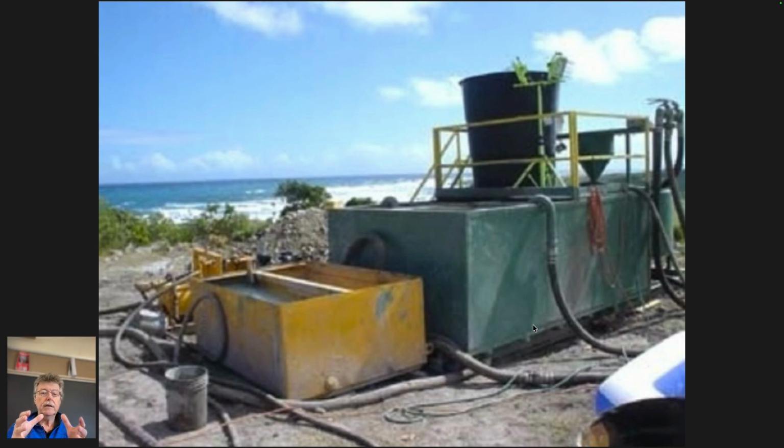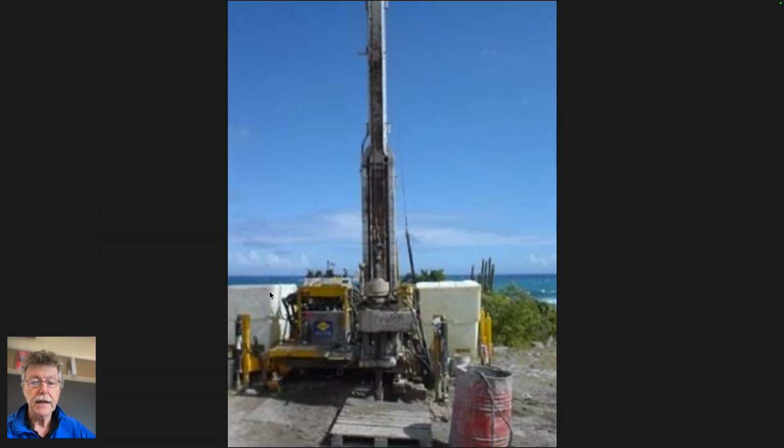Mud tanks to mix mud with bentonite. Bentonite is used to be able to make the water heavier because it takes on the density of the combined slurry, and it acts to better keep the hole open by putting a larger pressure against it if it's a larger density, larger unit weight. And it is also better to bring up the cuttings to the surface, because you know that when you try and move something with flowing water, the drag on that is proportional to the density of the fluid and the velocity squared, right? And what's the Euler number, in other words, from fluid mechanics.